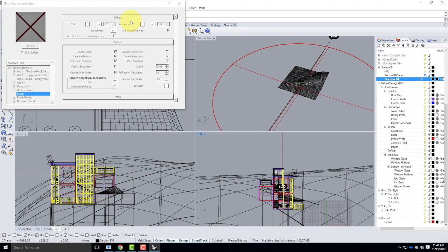And give it a little bit more time. Come on, V-Ray. That's the layer that the SectionTools made that has some of the objects on it. When the SectionTools cut the section, it's supposed to fill in any solid objects with surfaces. It didn't do everything, but it did do some of it. Okay, so obviously it's not saving, so I'm going to close Rhino and save Rhino and then open it again. Apologize for that.